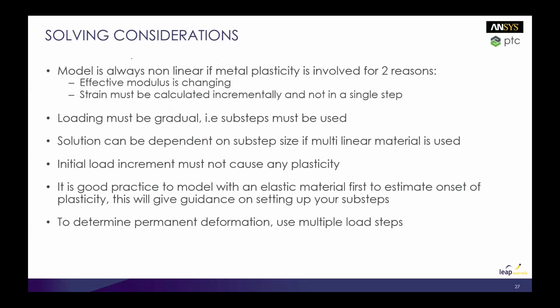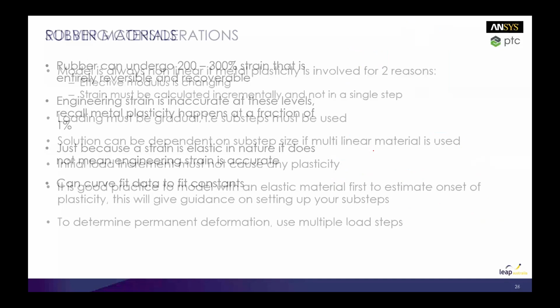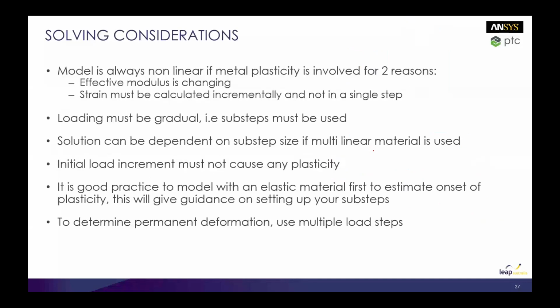Okay, so when we have a model with plasticity or large strain, we always need to solve it incrementally. Because we're incrementally calculating the strain, you need to capture that with solve points. So the loading has to be gradual.